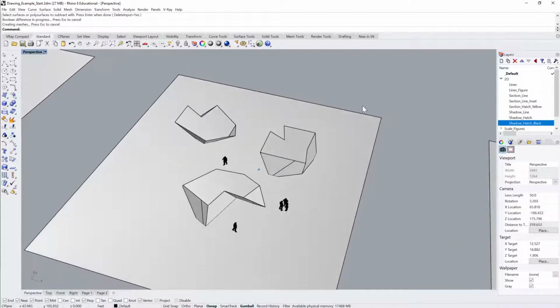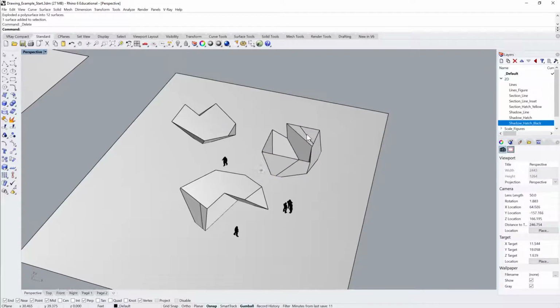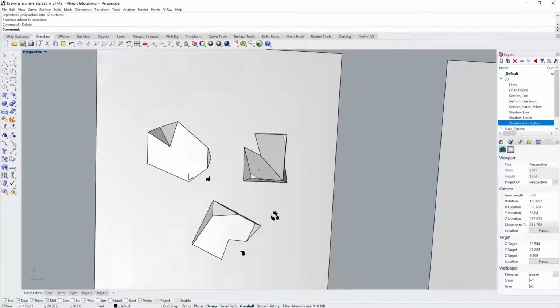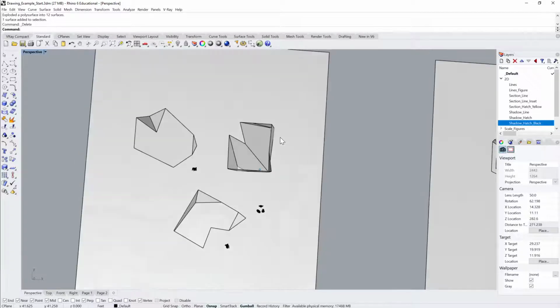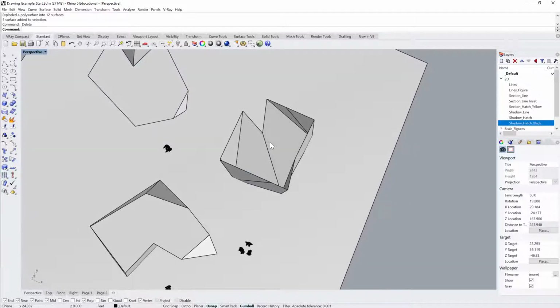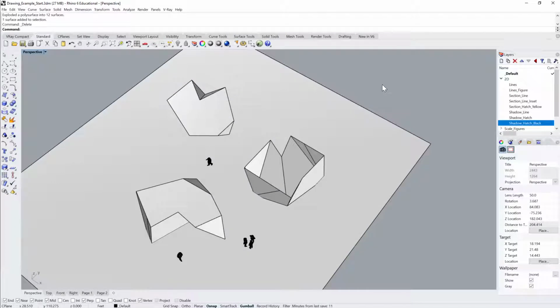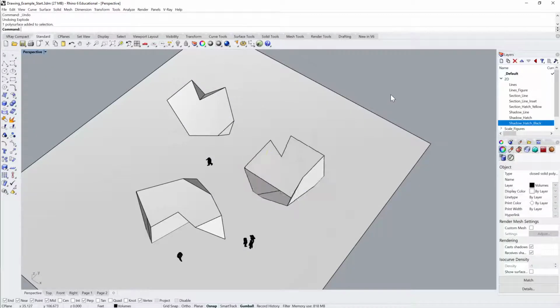All right, so how am I going to give this thickness? Now, you could fake all of this. You could just explode this, take the top off, right, and make 2D from this. But then once you draw your thickness in plan, these lines, the interior elevation of what you're looking at, won't match up, right? So let me undo that and make sure that's all one solid.